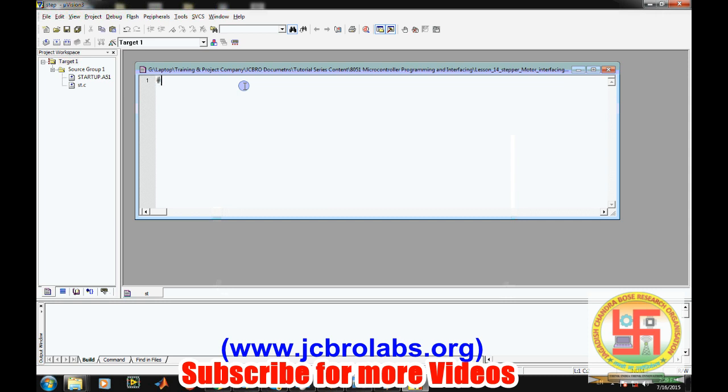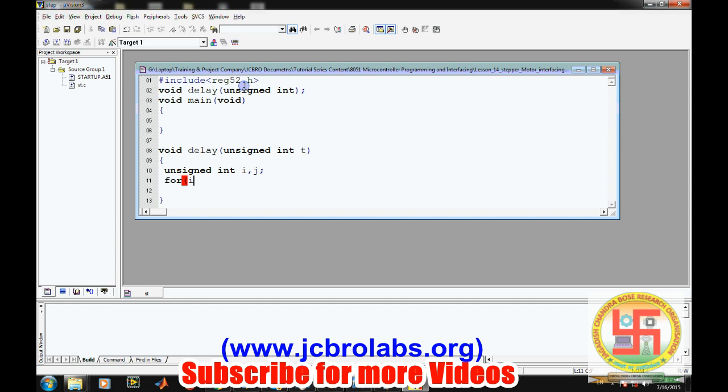Writing the program is very easy, as we'll see. So include reg52.h and then provide a signature for the delay function. It is the same as we have discussed in so many programs. Void main void, and then void delay unsigned int t, and then unsigned int i, j; for i equals 0, i is less than t, i plus plus, then for j equals 0, j is less than 1275, j plus plus.